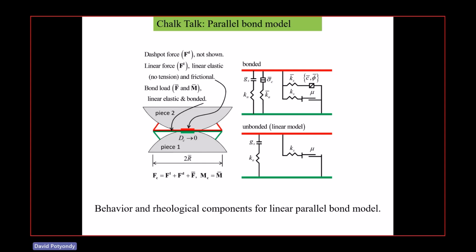Okay. And then the same thing, this thing can break in shear. So it has a shear stiffness, and the shear strength, here's that fuse, is going to be expressed in terms of a micro cohesion and friction angle, which means that strength is going to be a function of the confinement as well. Okay, so those are the parameters then.